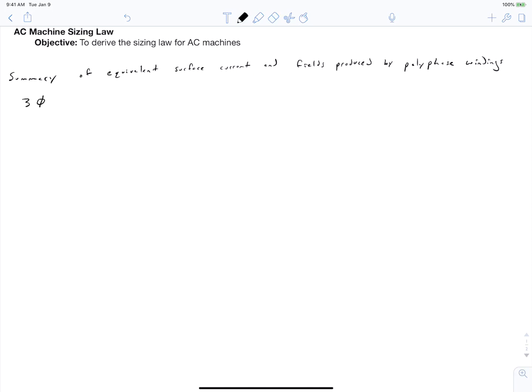We've talked about our machine being excited by balanced three-phase currents, and we've written expressions for those currents as follows, where these are cosinusoidal expressions that take an argument, in this case, of alpha W. In our video on this, we had written alpha W as an expression of omega t plus a phase. In this discussion, we're just going to consider it as having this argument of alpha W. It does not have to be in this form. It just has to be that IU, IV, and IW are cosinusoidal currents that are phase shifted from each other by 120 degrees and have the same magnitude.